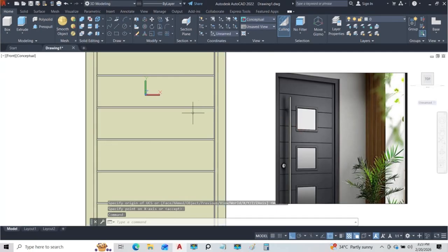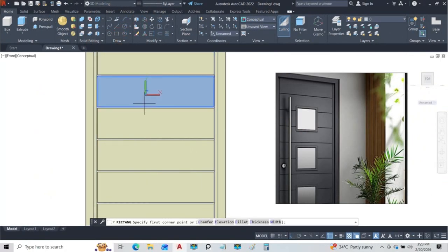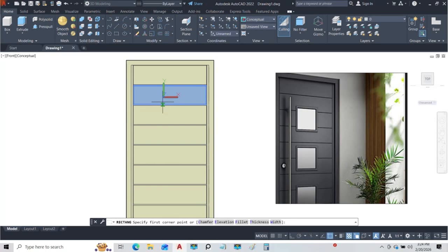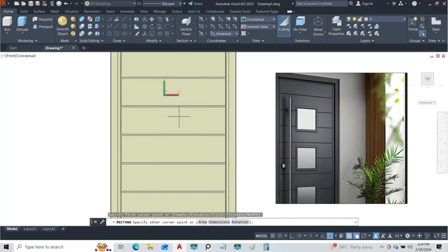So we want to create a rectangular shape on that surface. Let's just say here we're not giving any dimension whatsoever. So let's just click here. Let me get the length straight first from here to here. That's, let's say 200. Okay, so we'll go to this place, click somewhere here, and before I draw, there's an option for dimension. So it's asking for dimension 200 by 200, and then it's asking for where we want to put this, which I can just put here.